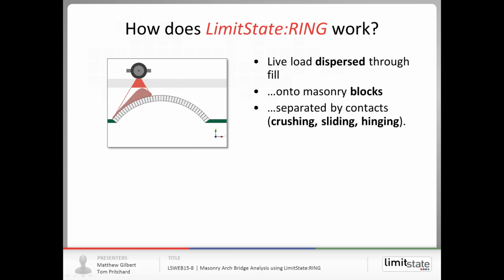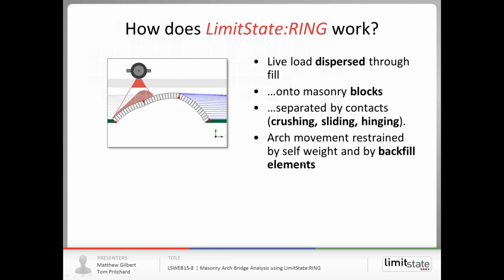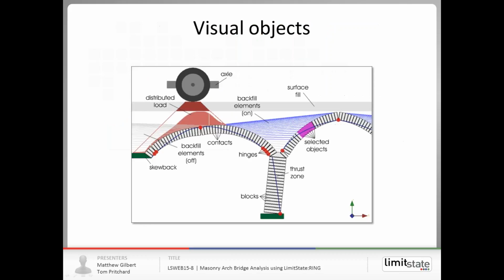Those masonry blocks are separated by contacts, and the contacts are actually where a lot of the interesting stuff happens. We can model there potentially sliding, hinging, and also crushing of the material. And then movement of the arch barrel into the surrounding fill is restrained by self-weight and also by backfill elements that we can see here in blue in the diagram.